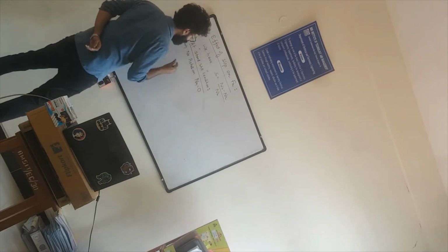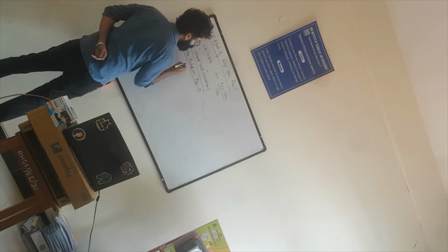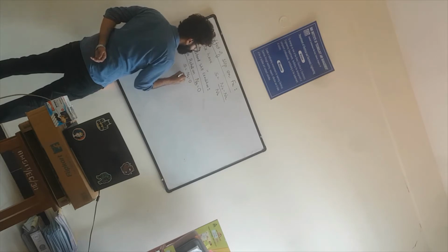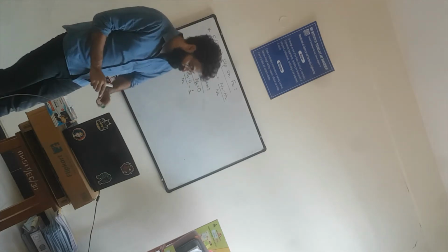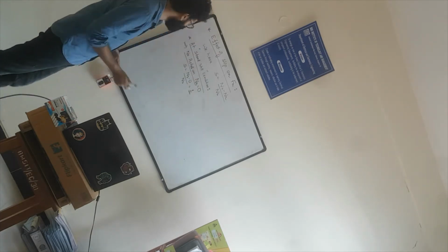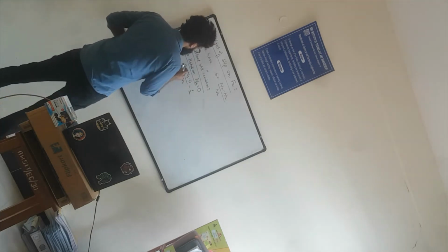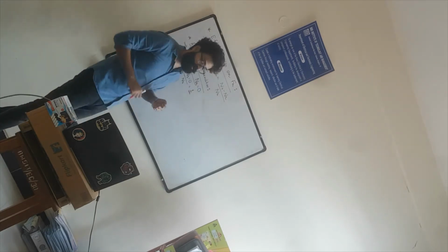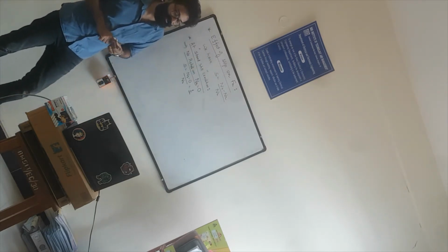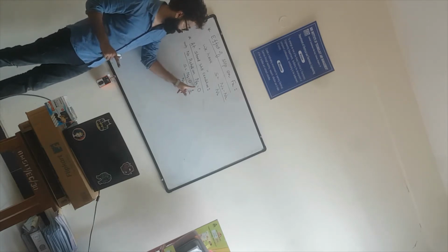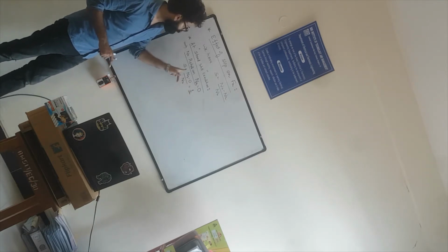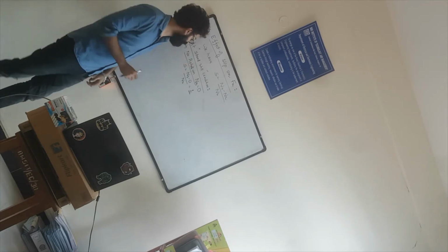What happens to slip? When there is no rotation, slip S becomes (Ns minus 0) divided by Ns, which is equal to 1. So slip becomes 1. This is very, very important. The other way of asking the question is: when do you get unity slip? You get unity slip when the rotor speed is 0, and this particular condition is called the standstill condition.